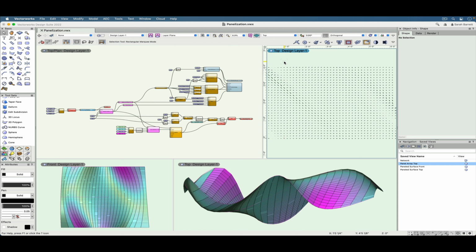The color is useful for a visual understanding of the design, but numerical data is important too. The script also creates a worksheet that lists the panels by ID number, distance out of plane, i.e. the distance that the 4th vertex of the panel is out of plane from the other 3, and the total area of each panel. This is a little different than the last example I showed of the floor tile array. That script did not generate its own worksheet, but it had data that I could easily extract. So this script has the schedule built in.